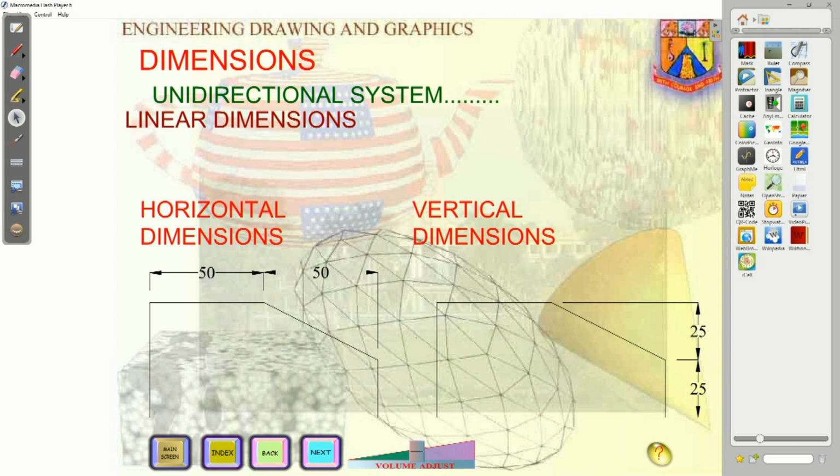This is one end point, and this is another end point. Taking these two end points, from these you have to draw extension lines. This is an extension line, and this is another extension line. Sometimes this extension line is vertical or horizontal, because we have chosen linear dimensions. Normally we draw the extension line from the object endpoints, but you have to give a space between the object points and the extension line. This gap should normally be about 2 mm; don't choose less than 2 mm.